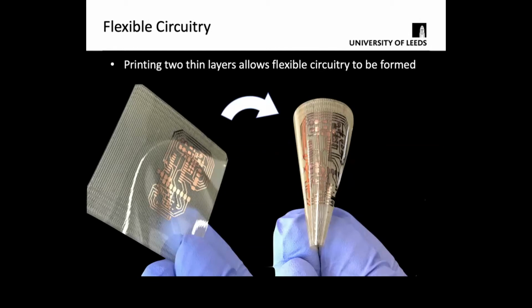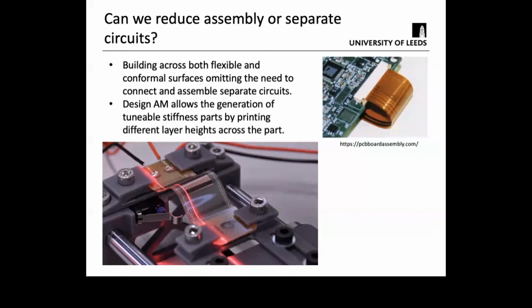But when you look at traditional printing of inks and paste onto 3D printed substrates, you might be able to get something that bends, but once you bend it a few times, the material starts to delaminate or the conductor cracks, so you get some other failure. So we wanted to validate this. So the next thing that we started to look at was to say, okay, well, let's bend test these structures.